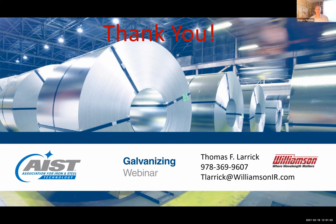Thank you, Thomas. If anybody has any follow-on questions, you can submit them through the question and answer element. And we do have one that just popped in. Which pyrometer is the most accurate in a galvanizing furnace, radiant tube furnace? Yeah, again, it depends upon the measurement technique. If you're using the roller wedge technique, then we recommend the dual wavelength technology. And if you're using the direct view technique, then we recommend the multi-wavelength technology.